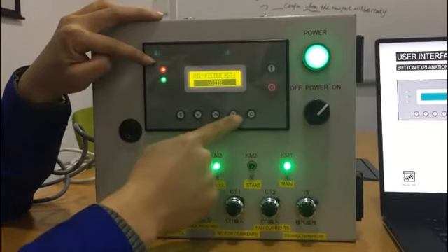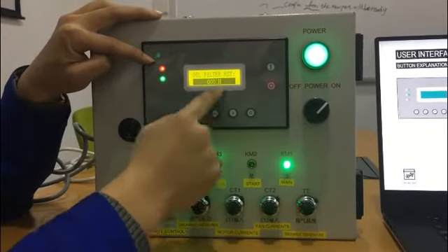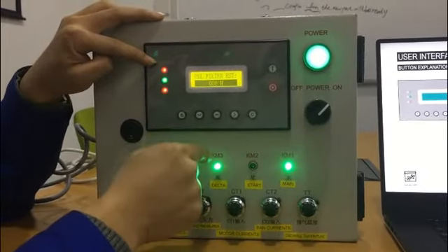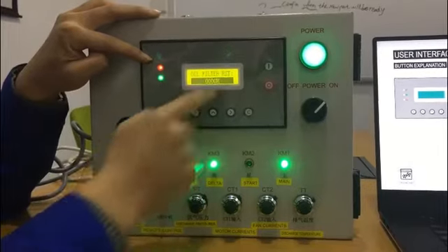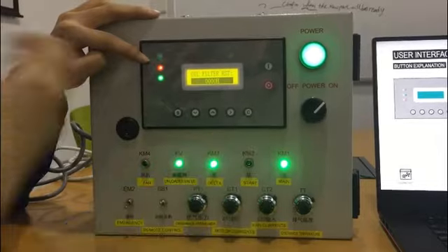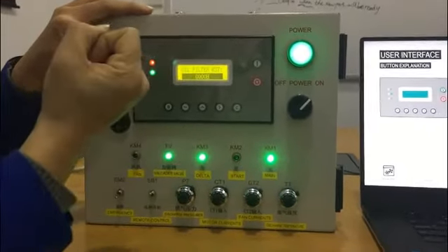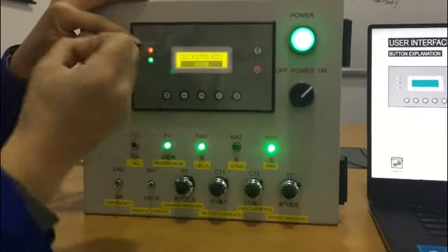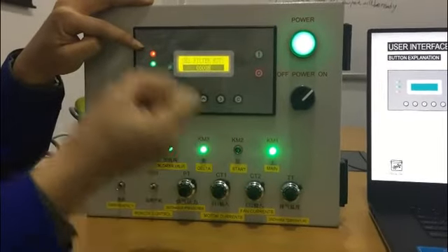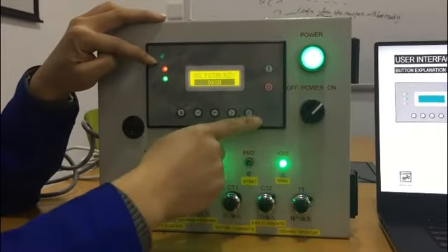Press the enter button and change the value to 0. Confirm, then you can cancel the alarm. Of course, we set some alarms for our consumable parts, such as oil filter, air filter, lubrication, grease, and so on.